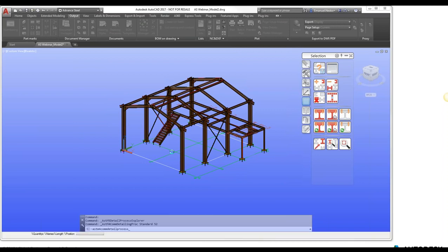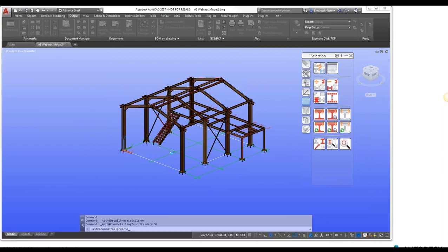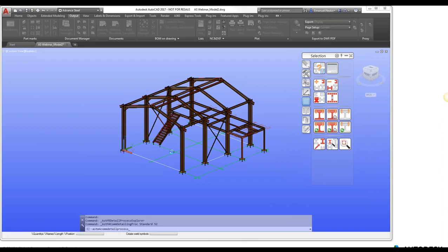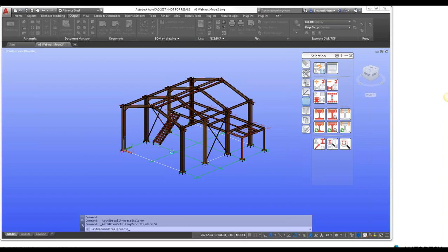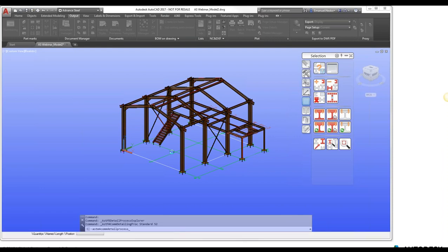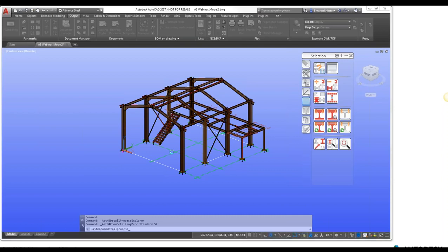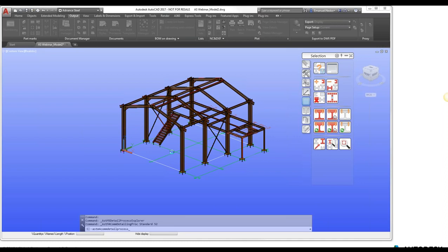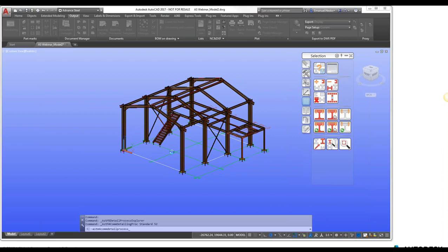Alright, in this case it will take a little bit more time. What is important when we are using a drawing process is that it can use different drawing styles for different elements. In this case, for the beams, it is able to use one drawing style, while for the bracing it is able to use a different drawing style. So it's much easier to configure a drawing process with the rules to be used during the detailing and then just use the drawing process.